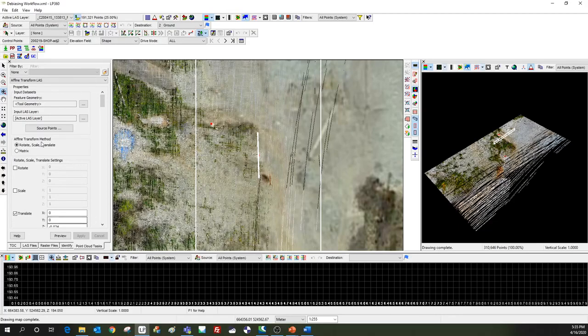So what we're going to be doing here is generating a new LAS layer. When we do some additional processes, we want to make sure we switch to the correct LAS layer. And if we have this button depressed, we can make sure that only one LAS layer is being displayed at the time. We're not choosing our original LAS, so we won't get all confused. So just keep that in mind, and you'll see that in a little bit.